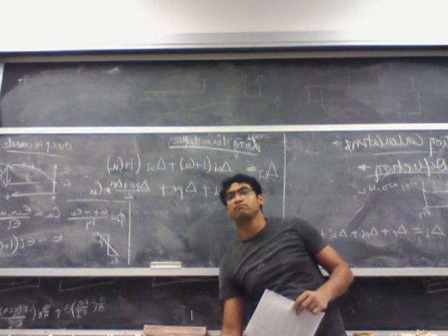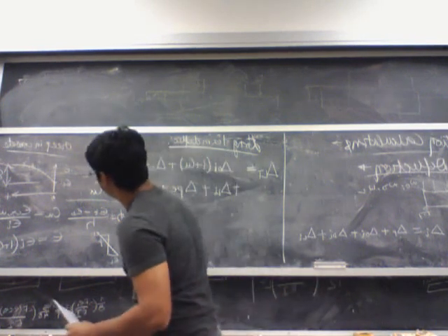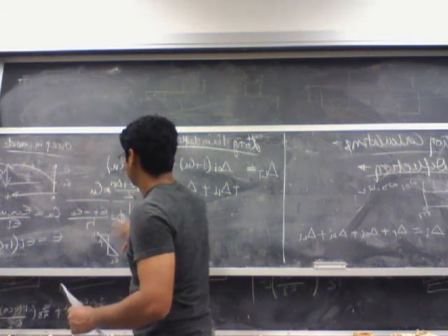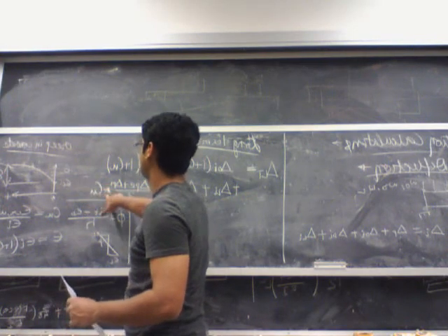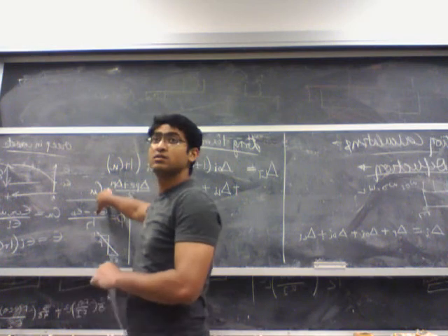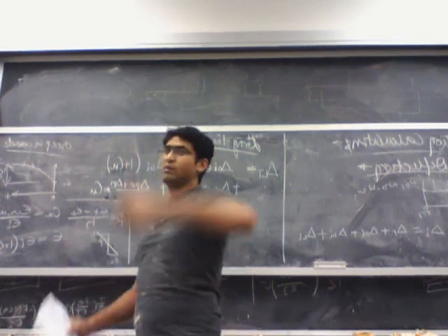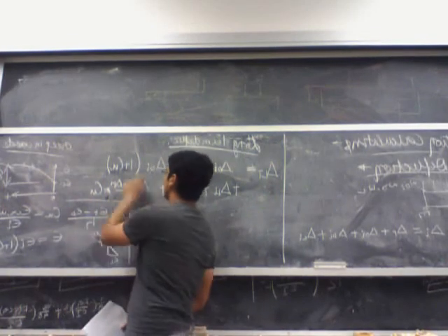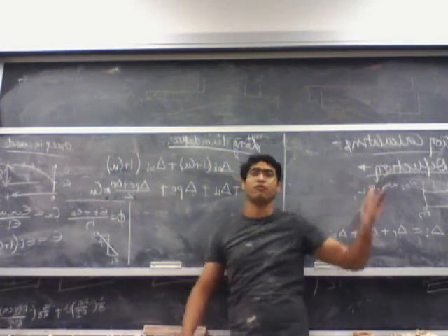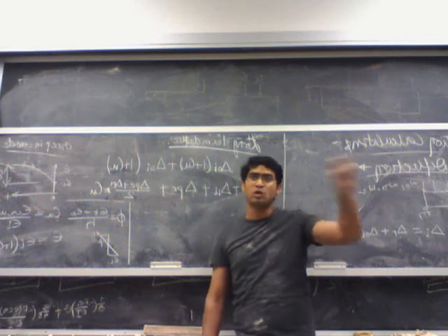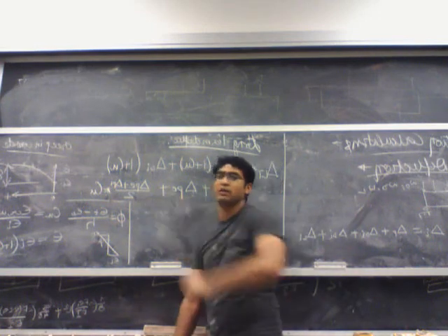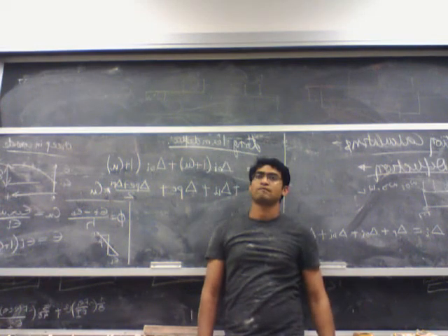So that term, the last term, is increased deflection upwards. Where? The last term. This one? Yeah. So because we can get more deflection upwards. So it will keep on. So these two terms will be negative depending on what your strand profile is. So if your strand is below the centroidal axis, they both are actually negative values. So your creep actually helps to increase the upwards deflection.